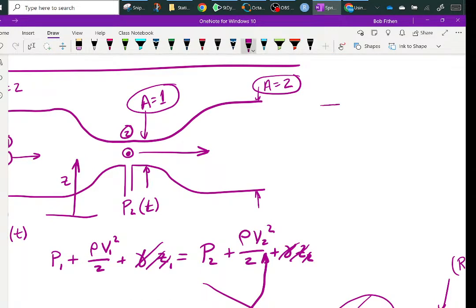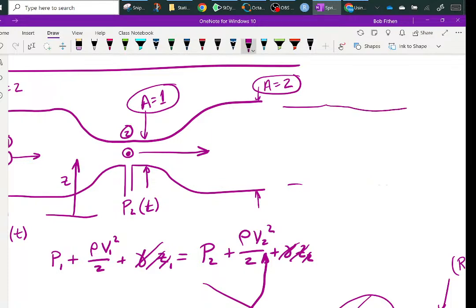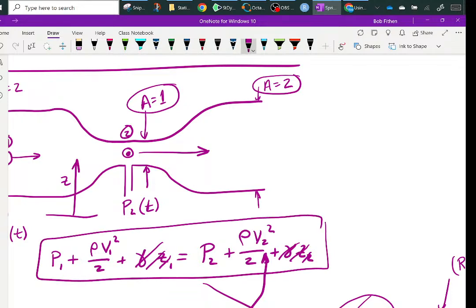The last thing you want to do is do like this and restrict your flow. You're looking at the pressure difference between those two, but you've restricted your flow so much that you've slowed it down. And if your area change is too tiny, when you put your taps there, you're going to end up with not a very accurate picture of your flow rate. So it just depends on your circumstances. But the key is we just use this to relate those two.